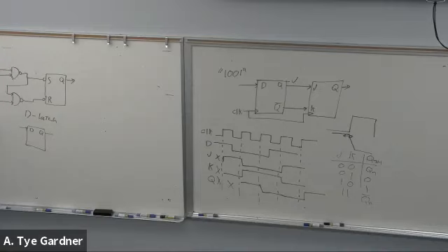It's an enable. That's all, right? If it's on, these two NAND gates can work. If it's not on, I0 is just ignored, the D input. So, enable, as an enable input. It's a D latch with an enable.